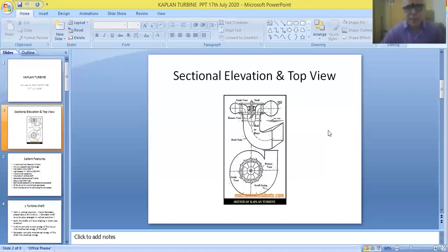And friends, this is about the construction of the machine. Now coming to the working of the machine, as I've already told you, the casing of the turbine will be fitted to the penstock that is coming from the first reservoir, the dam. So water coming out of the penstock will be entering the casing, and it will be flowing in clockwise direction.